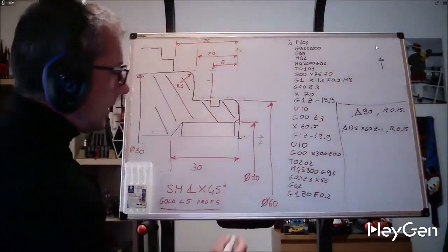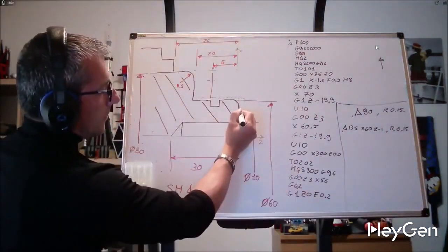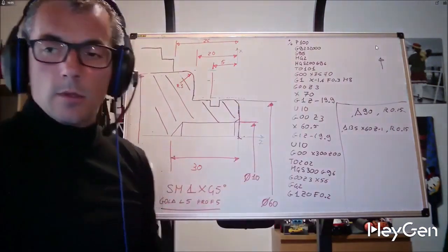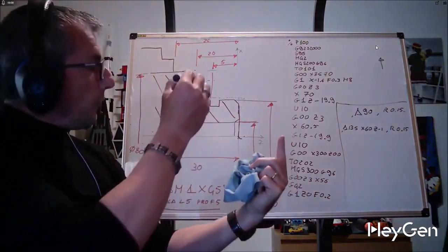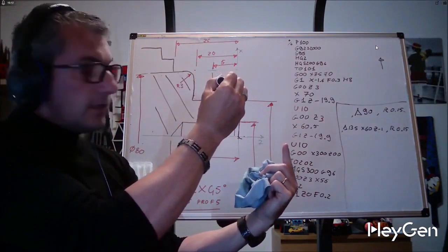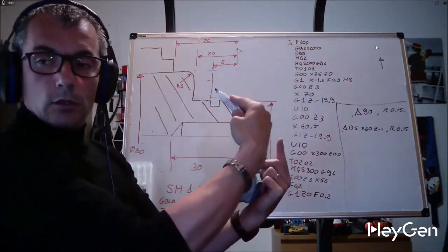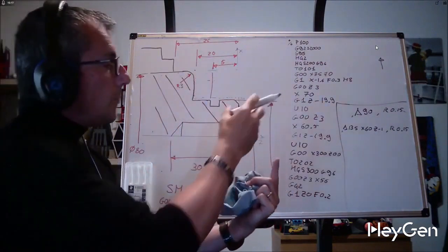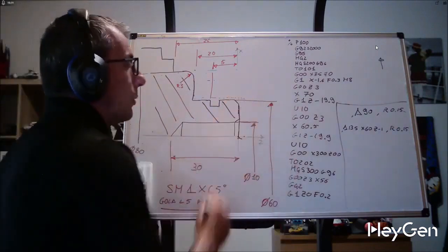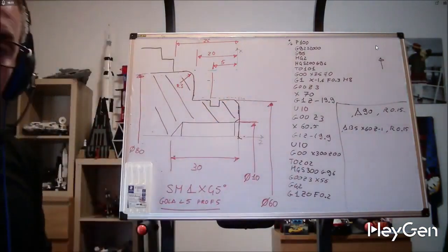I go to X 56, Z 0. I'm here, then I tell it to go up at 90 degrees. I give it some information: you stop at Z minus 1 X 60, and you reach 135 degrees, which is 45, and in both cases, it finishes the trajectory with a 0.15.